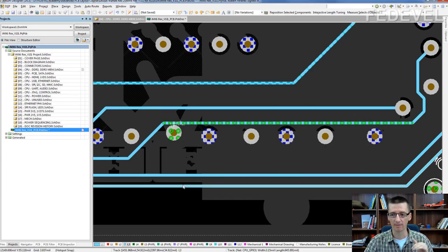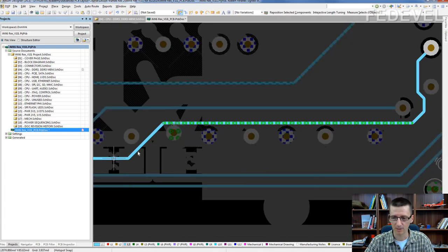In phase 2 it is different. In phase 2 keep your PCB clean from violations. It is good for your psychic state because you will see the PCB is still fully routed. Everything I need to do is just this small tweaking. If you don't clear these violations in phase 2, after a few days your whole PCB may be green again, and then you will see, oh, there is still a lot of work. So in phase 2 you do it like this. Okay?